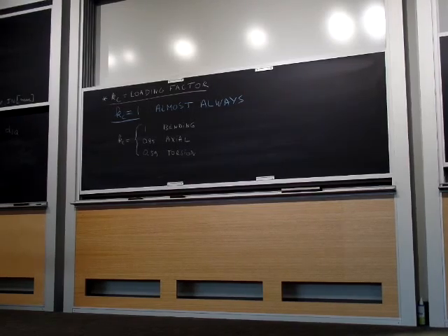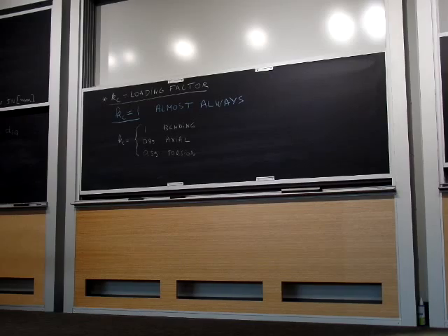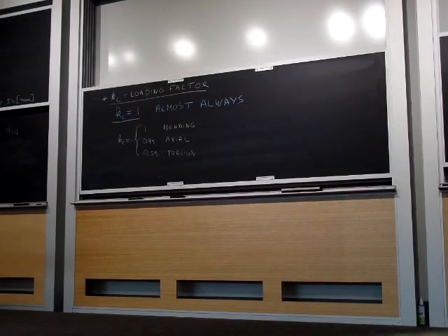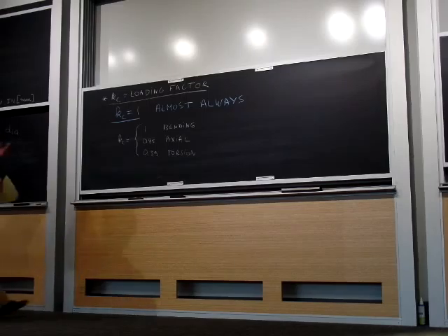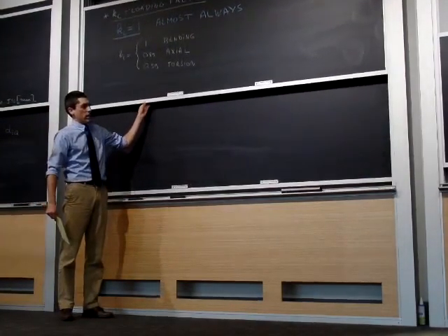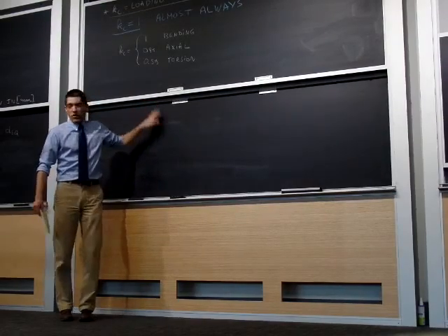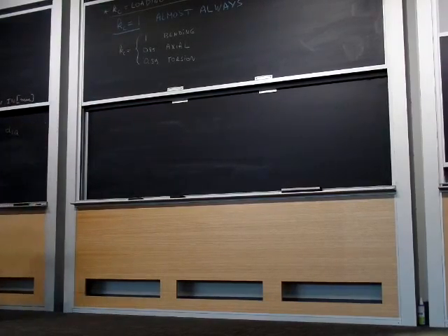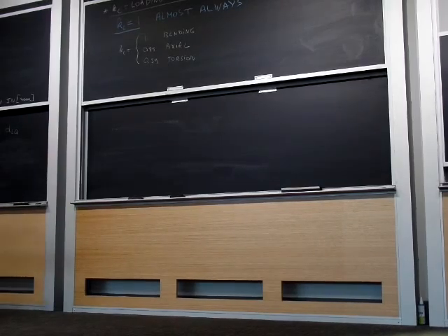If you have combined loading, which is almost always the case, then KC is equal to 1. And we'll account for the different types of loadings, and you'll see that we'll do example problems. We'll account for the damage that each different type of stress does to the part in another way, not with KC. So if you don't know, it's always safe to assume that KC is equal to 1. Okay? So if you doubt, if you're not sure, take KC equal to 1, and you're probably going to be correct.